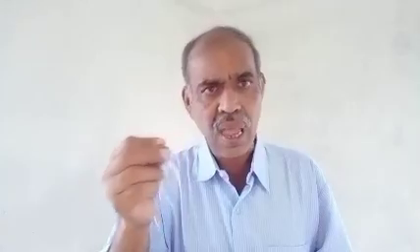So the product x dw which appears in the numerator means the weight, which is nothing but a force, so the moment of that weight about the origin. In the numerator there will be integration of x dw, in the denominator there will be integration of dw. So this is nothing but x bar.